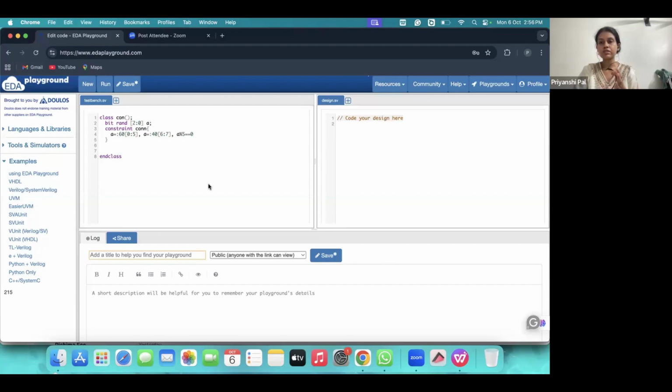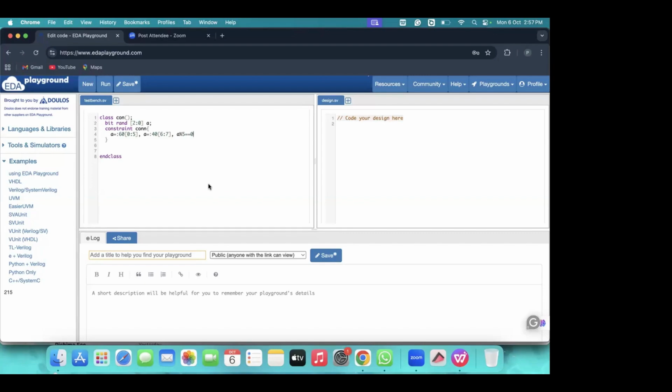Synchronous FIFO is a bit simpler and less complex. Asynchronous is a bit complex. We can use asynchronous FIFO if we want to establish communication between a fast speed peripheral and a low speed peripheral. Okay.